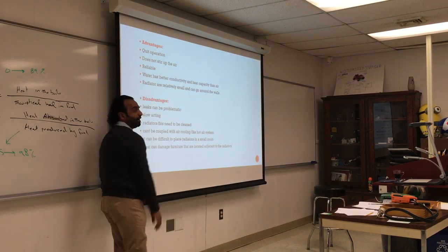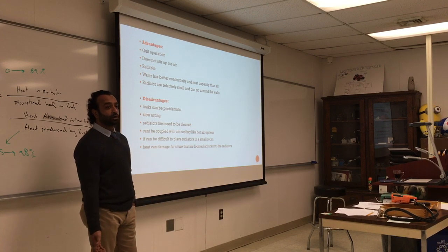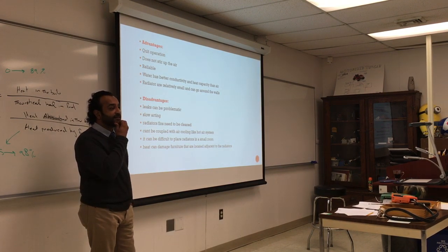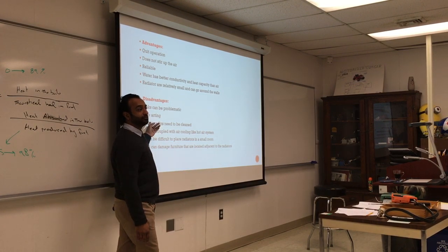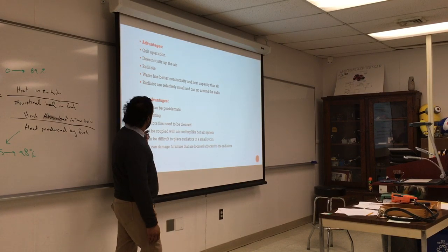And it's slow acting, relatively. It will take you a while to heat the water to 180. Then you have to wait to circulate the water through the rooms and it will start to dispense into the room. So probably it takes 20 minutes or half an hour to start to feel the warmth come up. Unlike forced air, where you just hit the button and you'll have hot air in 2 minutes.